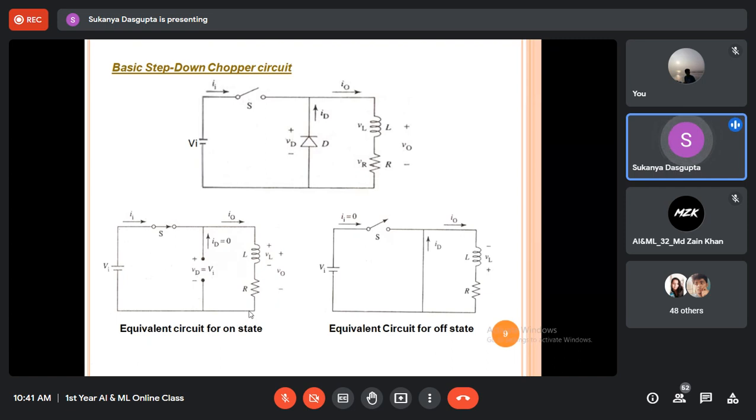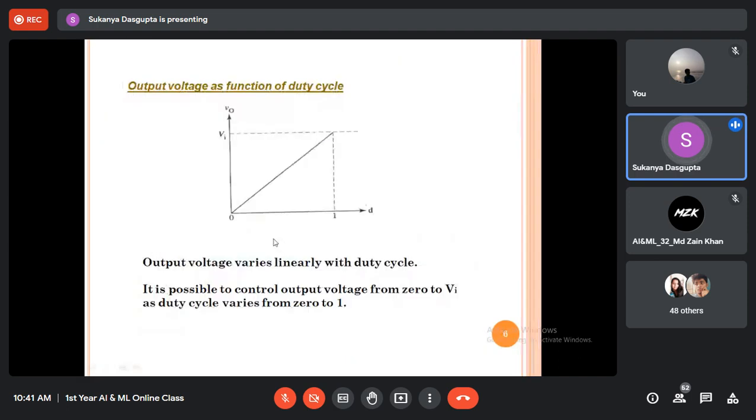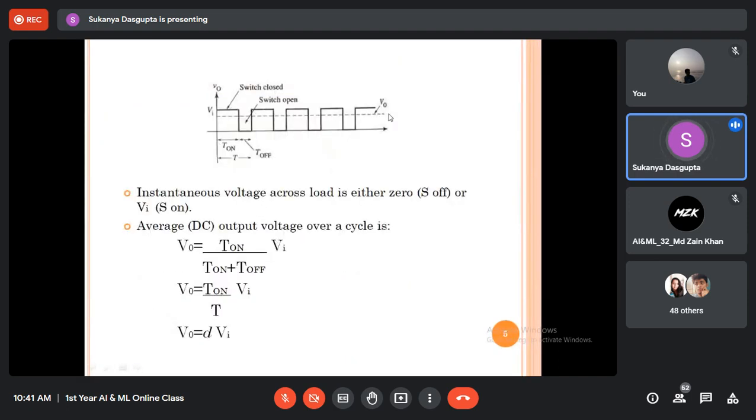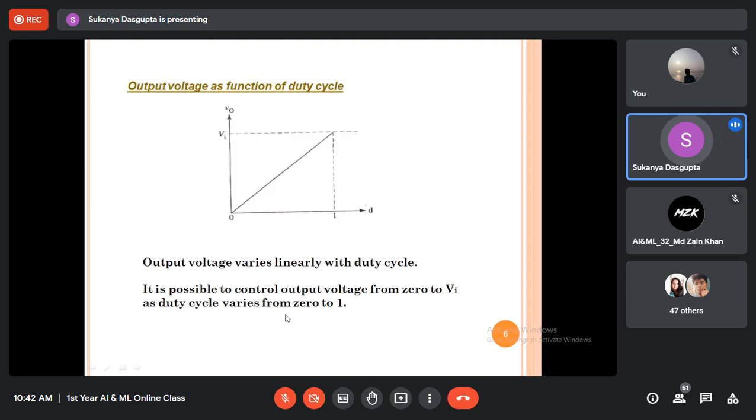Now automatically after some time, the switch will be left open, depending upon the control strategy or control circuit that we have designed initially for the gate terminal of this semiconductor switch, right? So as per the gating signal that I have shown earlier, this type of gating signal is required to send at the gate terminal of the switch present in the buck converter.